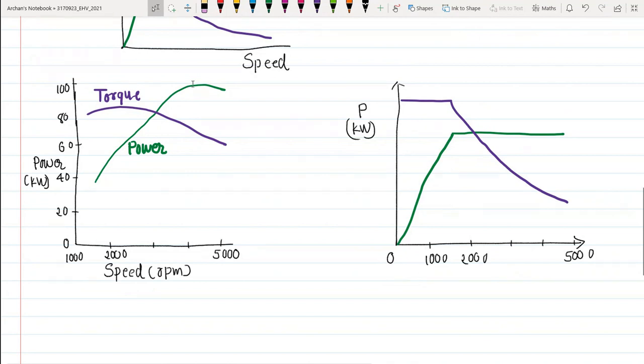And as the speed further increases, what will happen? The mean effective pressure will decrease, because of the growing losses in the air induction manifold and a decline in engine torque. Power output, however, increases to its maximum at a certain high speed.